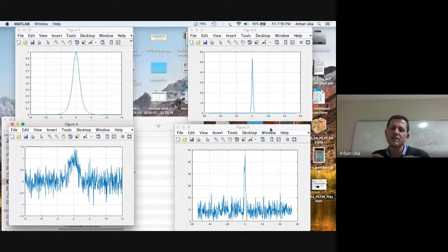What a box filter does is multiply with a kernel 1, 1, 1 over 3 data points. Let's say we have 3 subsequent data points next to each other. We convolve them with a kernel which is 1, 1, 1, which means that we're just adding them and dividing by 3. So we're taking the average.